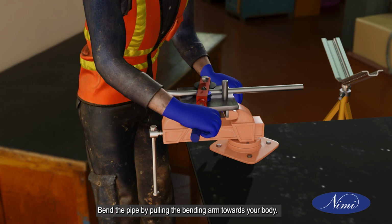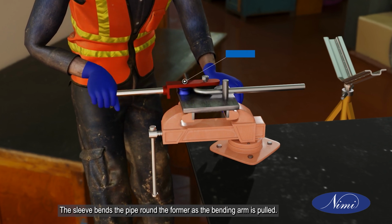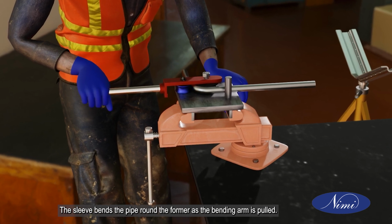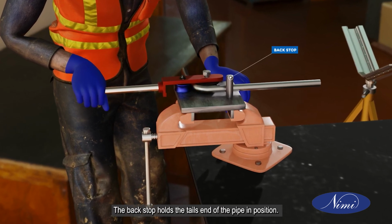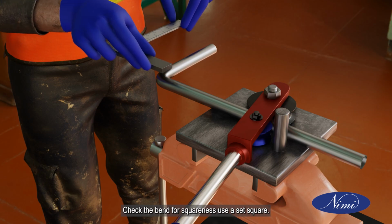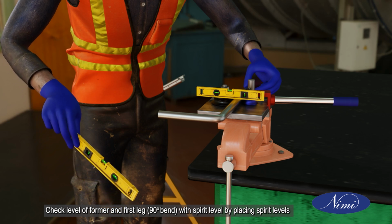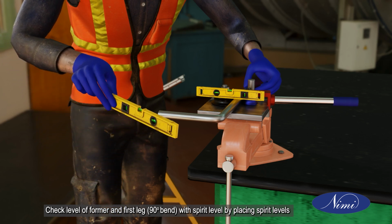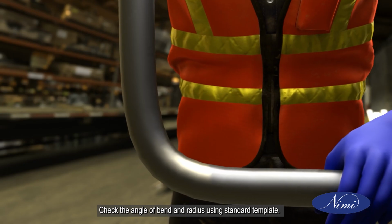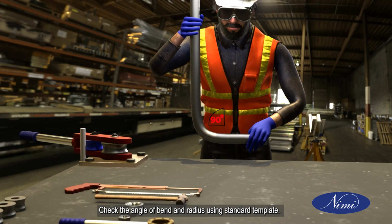Bend the pipe by pulling the bending arm towards your body. The sleeve bends the pipe round the former as the bending arm is pulled. The backstop holds the tail end of the pipe in position. Check the bend for squareness, use a set square. Check level of former and first leg 90-degree bend with spirit level by placing spirit levels. Check the angle of bend and radius using standard template.